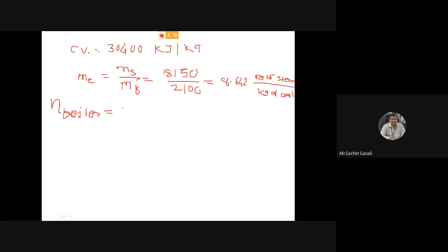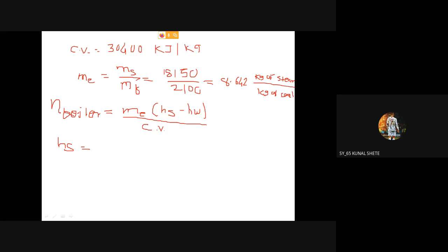The formula will be ME into HS minus HW, divided by calorific value. Okay. Calorific value we know, ME we know, HS. Now HS we have to determine. So what is HS now? We'll tell, HS is equal to, anybody? 2785.4. But what is HS?